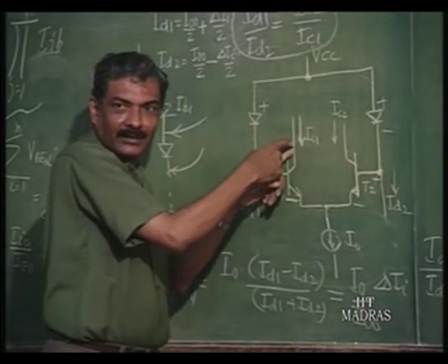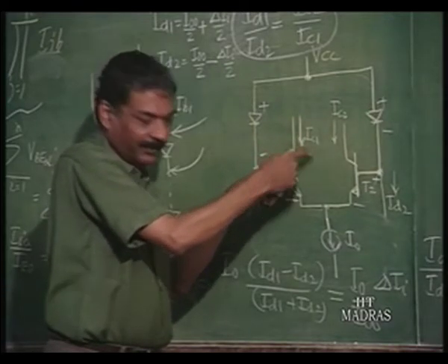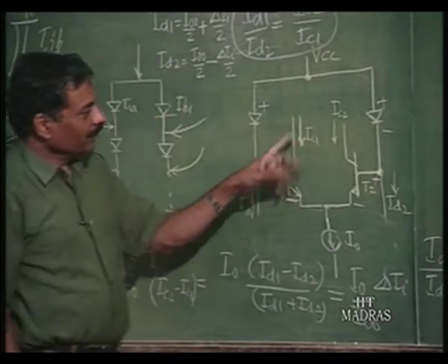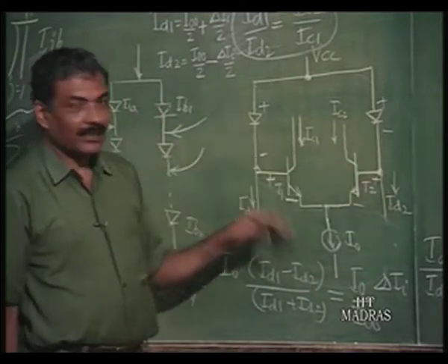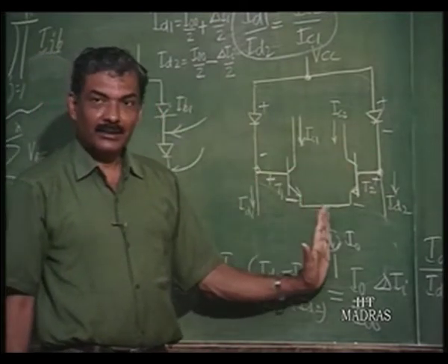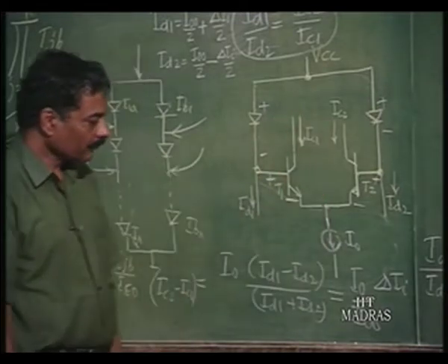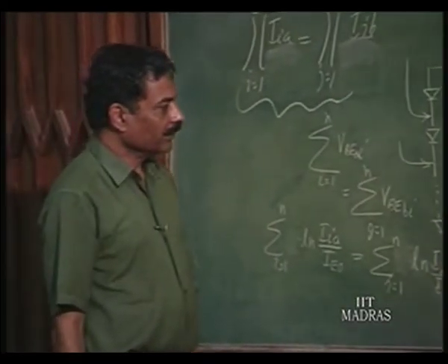The next stage will be having two other diodes connected to the same VCC with this as input now. This has now, as you see, a differential input and a common mode input. Common mode input is nothing but I naught. So, this can become the input to the next stage, and that will be exactly looking like this with this current operating at a higher value. That much should be sufficient for Gilbert's gain cell.